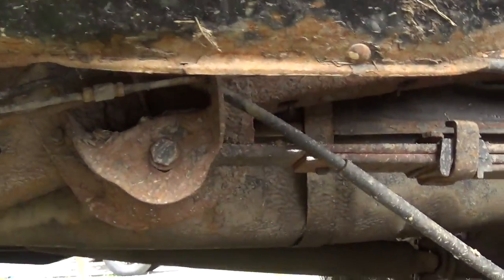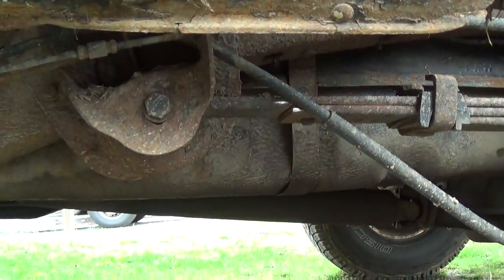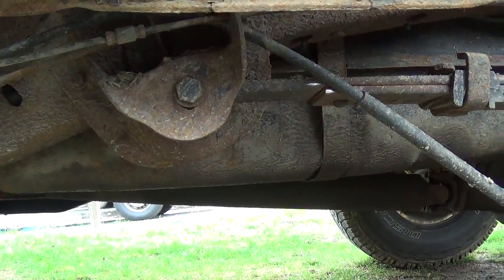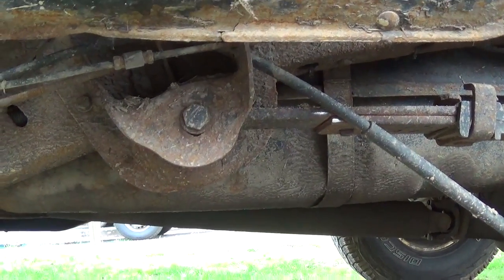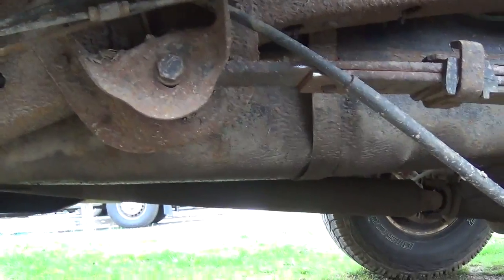And now it's just completely dead. I mean, it could be anything. Maybe a hose got disconnected inside the tank, but in this case, that's my diagnosis. Tank has to come off and replace the fuel pump, or if they find something there, then reconnect the hose, whatever. But that's it for now.